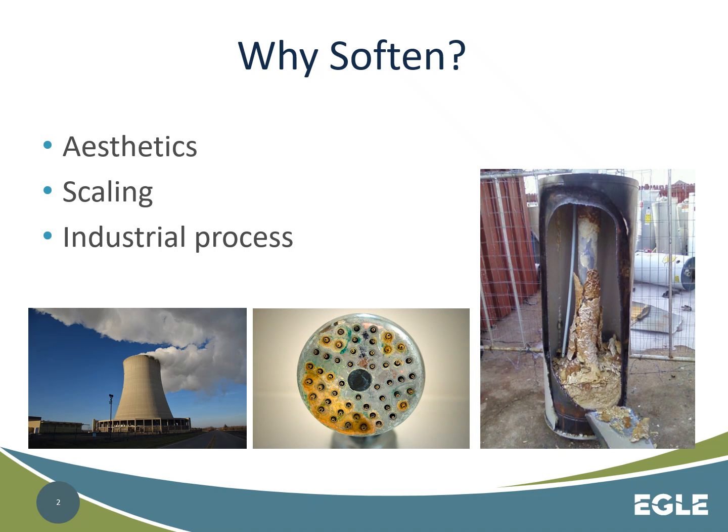Why do we want to remove it? Hardness can be a nuisance problem, like plugging up your shower head, or a major headache, like causing your water heater to fail, or even catastrophic in the case of a nuclear power plant cooling water. Removing hardness is not a health-based treatment. There is no requirement or regulation regarding hardness or calcium and magnesium. Removing hardness is a service provided to the end water user to make the experience more pleasant.